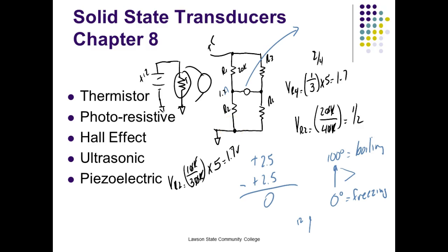It's the only element in the circuit. It's going to always be what? Plus 12 volts. Now, I could use current, but current is hard to use, right? You understand that? So what does that mean? Well, that means, by George, if I'm going to use a thermistor, I'm going to put a fixed resistor in series with the thermistor. Now, I can put the thermistor at the top, or I can put the thermistor at the bottom.